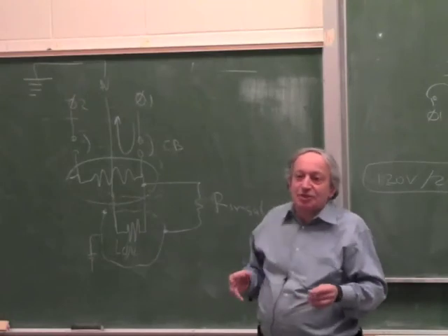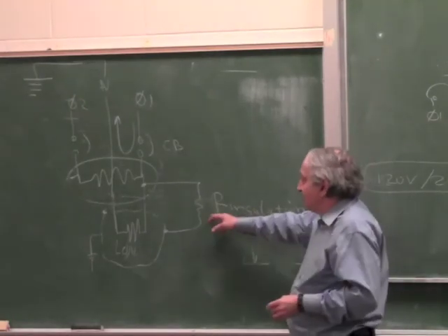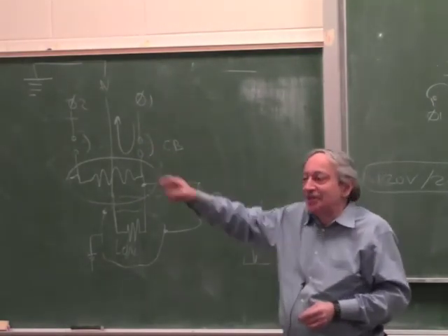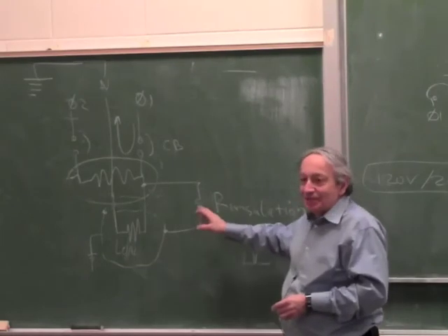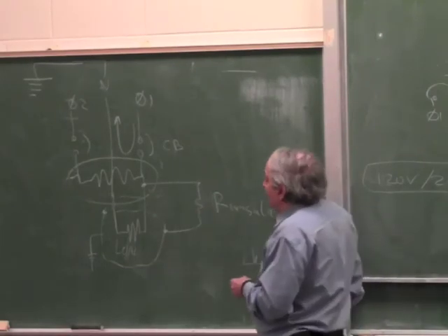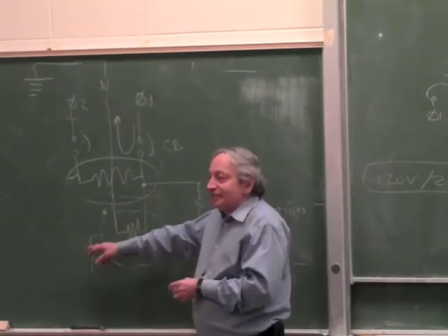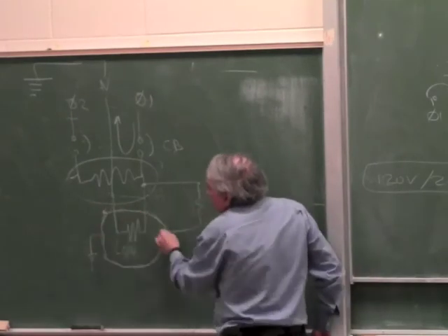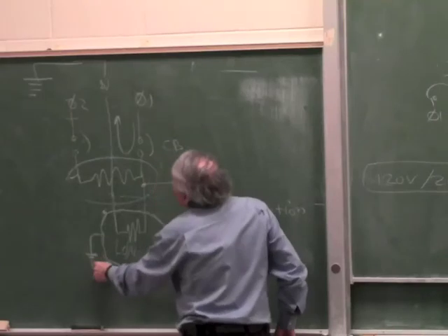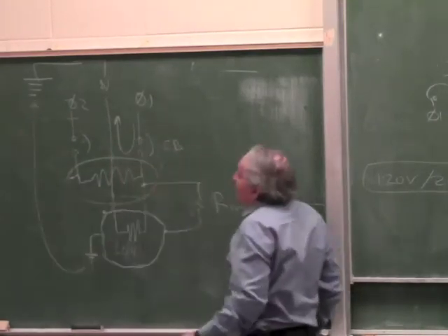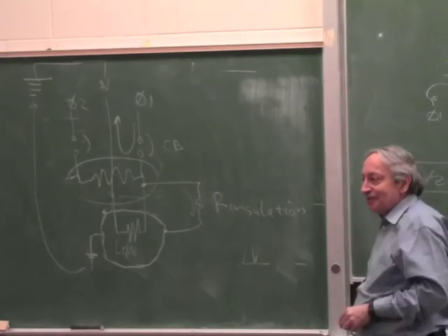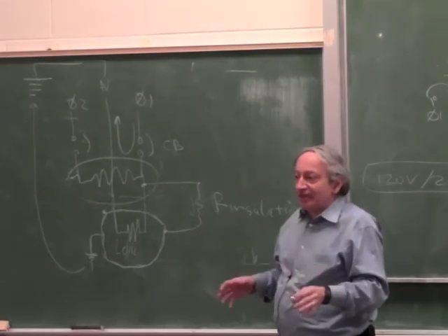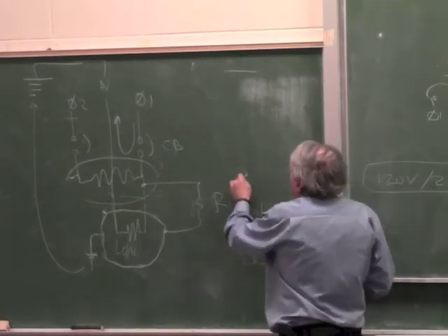And this happens because insulation is not perfect, and all the appliances in the house add up in parallel here. Because the neutral and the phase go through the whole house, and each appliance has a bit of leakage. So it adds up to some current. So there is actually some return current through the ground because there is some leakage through the insulation. This leakage is connected to the ground, and this current flows all the way outside the house because it wants to return to the neutral. Okay, this current can be significant. Like the electrical code says that this has to be larger than 1 megohm.